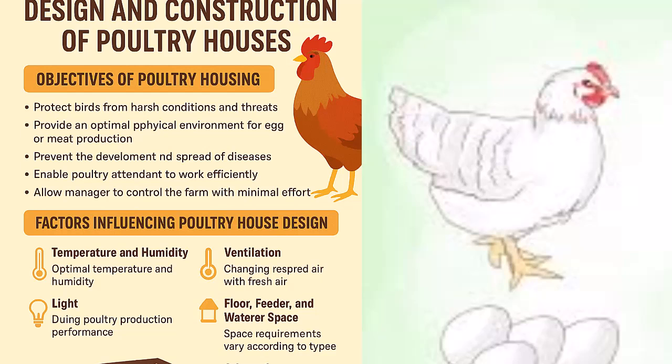Why should a poultry house be oriented east-west? To prevent direct sunlight entry and rain splash. What is the ideal humidity range for poultry houses? 40 to 60. Which of the following materials is best for roofing in a tropical climate? Aluminum or asbestos sheet. The width of an open-sided house should not exceed 40 feet or 12 meters.